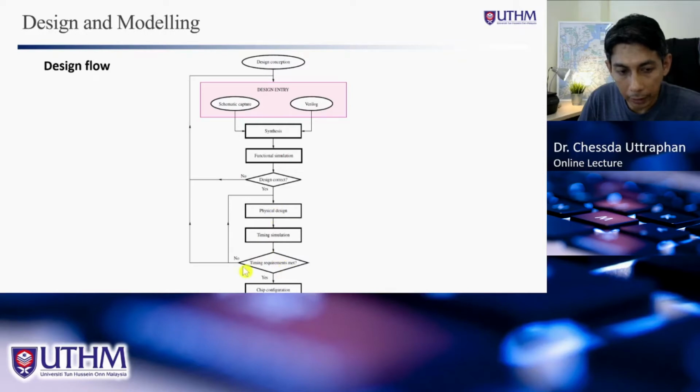And when our design passes the timing simulation, then we can do the actual chip programming, where we transfer our design to the actual chip. But if it does not meet the timing, we need to go back to redesign and look at the design again, whether we can improve the time, the speed, the performance or not, in order to meet the timing. So that is design flow.